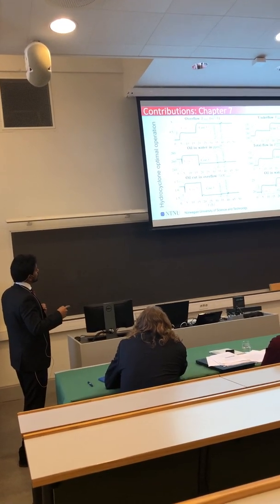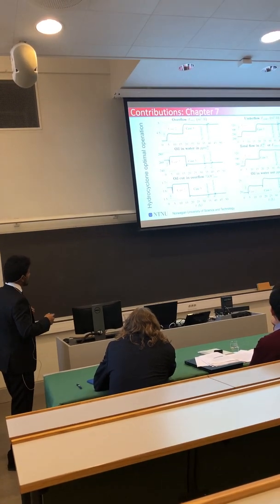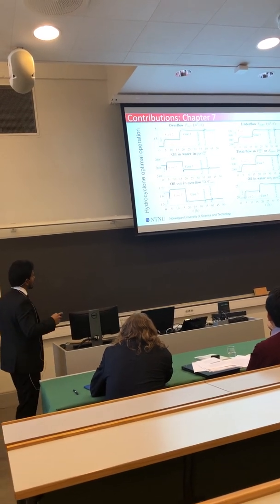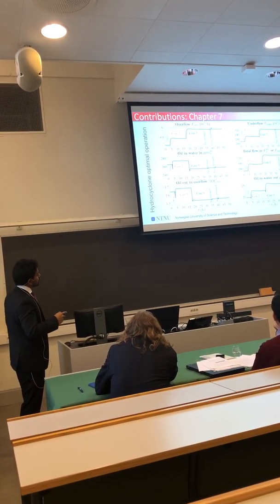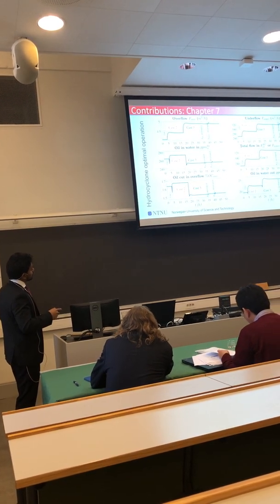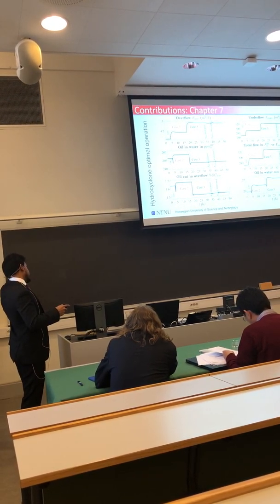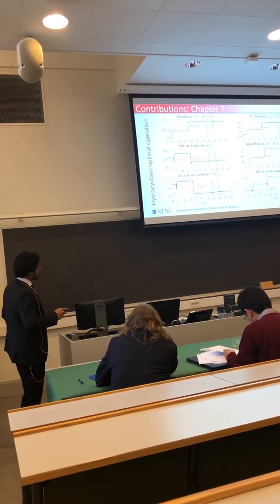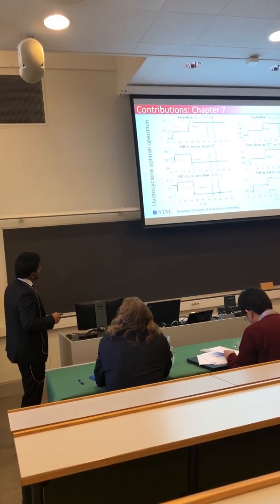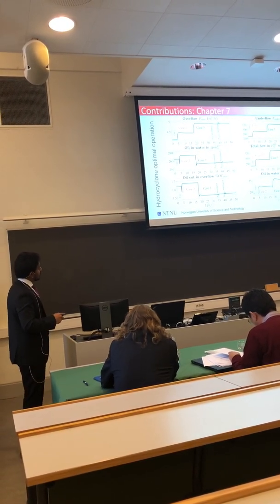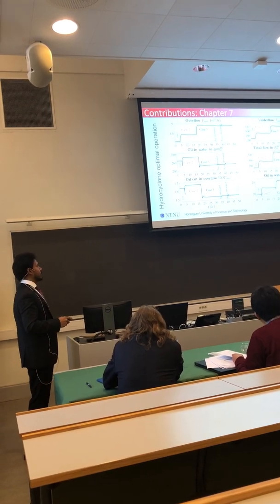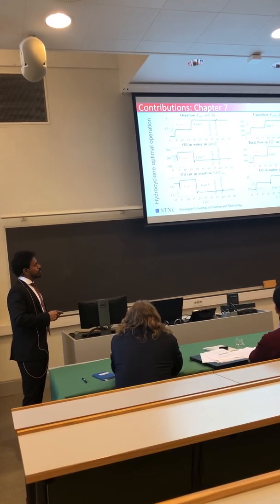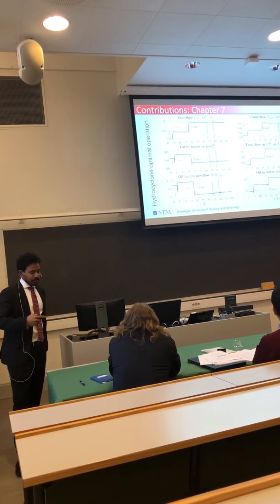For the overflow, we use a fixed flow split based strategy to control the hydrocyclones, and that's clearly reflected with the proportional relationship between these two, and accordingly also on the other flow. And then these two flows are summed up to this one, or this is this minus this. Then we have the oil concentration in the overflow and the water quality in ppm. So in the bigger superstructure I showed it's 19.5 to start with. It goes a little bit higher and further higher in case 2 and case 3.